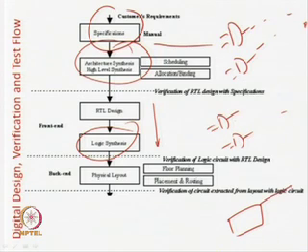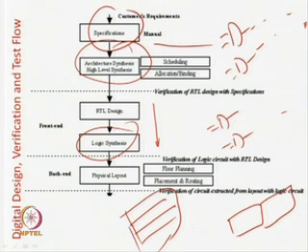Gates are basically rectangular blocks, and your die of the circuit will look something like this. It is rectangular or square in shape and it has some rows. Whatever gates you require, physically gates are rectangular blocks of different widths. So, you say this corresponds to gate 1, then this will correspond to gate 2, and maybe some other gates are there, so this will be gate 3, this will be gate 4.